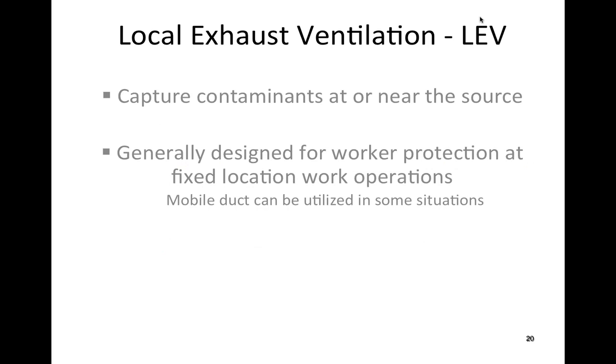Capture velocity: we have particles and junk like that in the air we want to capture. The velocity that you need to get that particle and pull it into your exhaust hood is called the capture velocity. Seems pretty obvious. Now, once it's in the ductwork, you don't want it to settle out. You want to get rid of it. Otherwise, you're going to have a lot of that build up in your ductwork. You need to maintain a certain transport velocity. The minimum velocity you need to keep it moving through the ductwork is called the transport velocity.